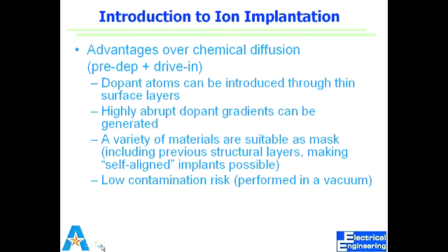They can be used to confine the lateral dimension of the doped area. But it will taper at the edges, right? So you'll have a smaller amount of dopants going through, and gradually no dopant at the edges. It won't be a straight vertical line. That's something we'll see.